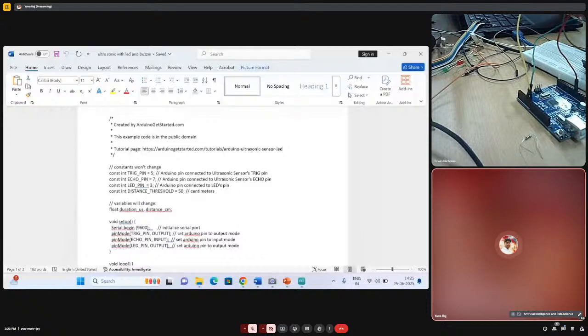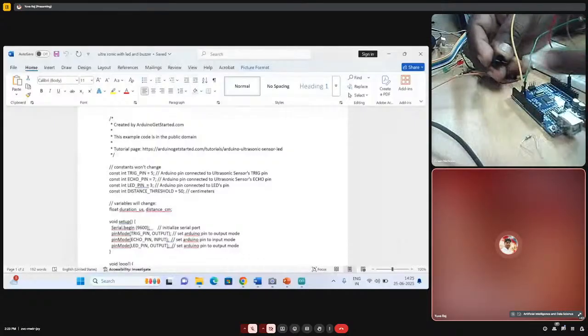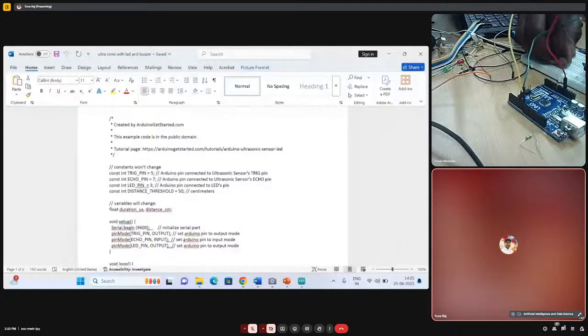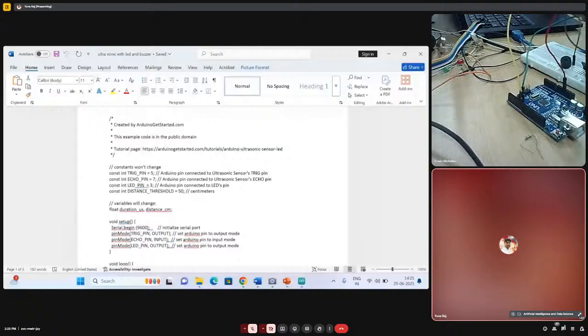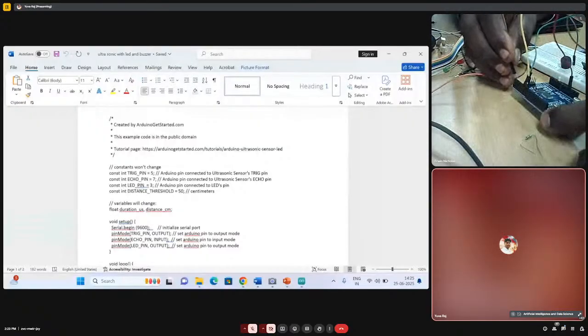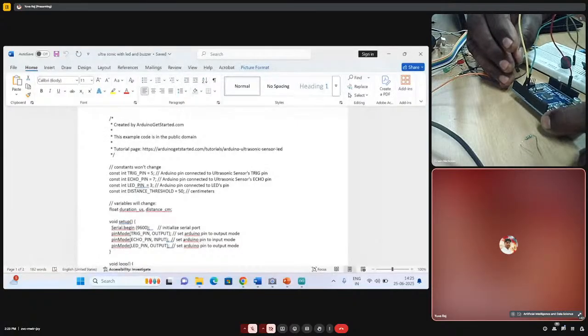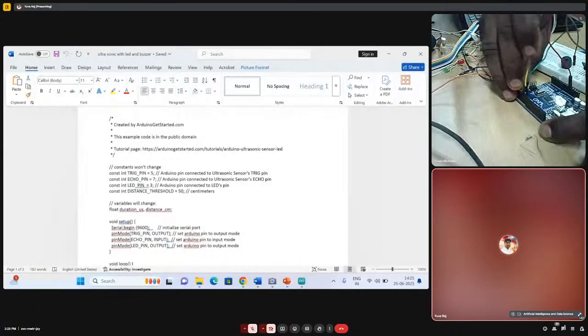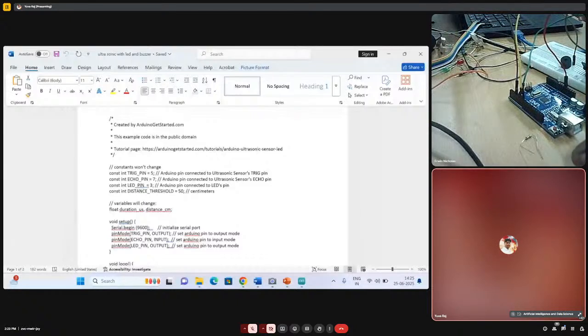Next, you are going to change the LED into the buzzer. The longer leg is positive, the smaller one is negative. The pin number is 3. Positive will be connected to 3. So the pin connection is over. In all, 4 pins are connected.